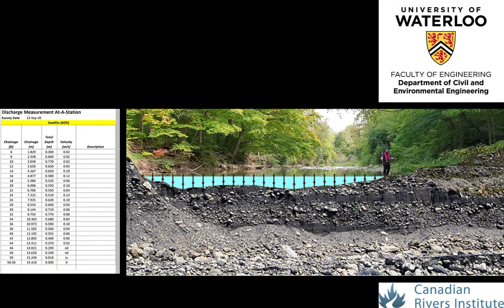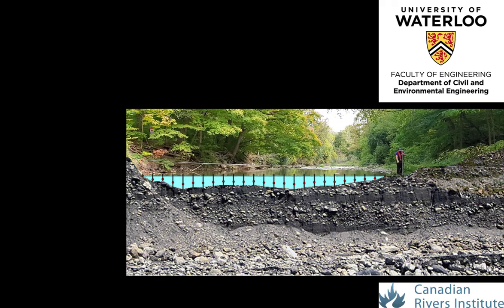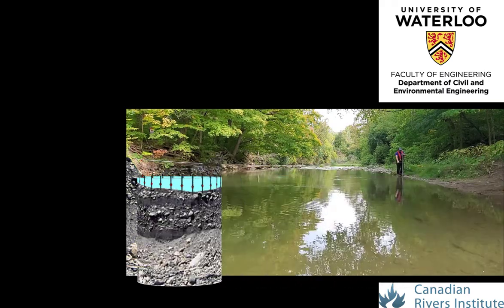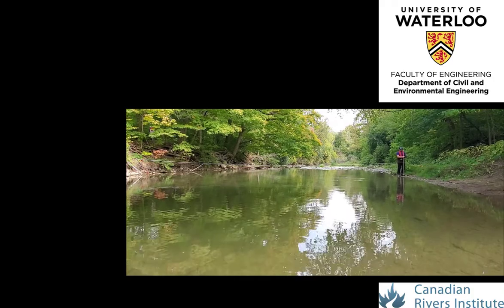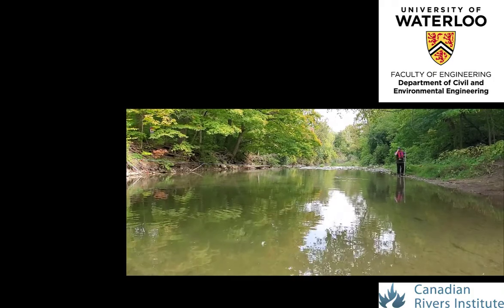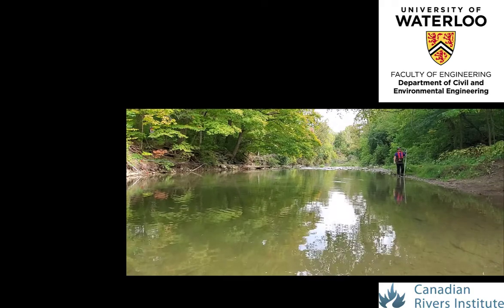Finally, the water's edge at the right bank of the cross-section is recorded at 50 feet 7 inches and is noted in the description column, concluding this part of the field measurement campaign. In part 2 of this video, we will post-process the data and apply different techniques to calculate panel discharges and the resulting total flow. In addition, we'll also explore alternative velocity representations and demonstrate how a field calculated discharge contributes to a rating curve.